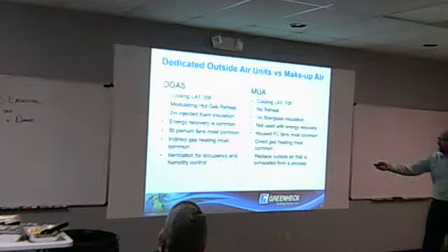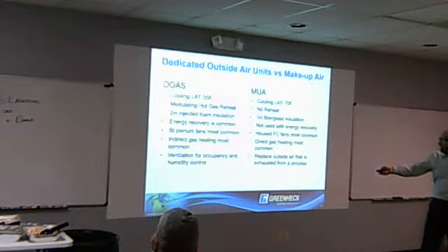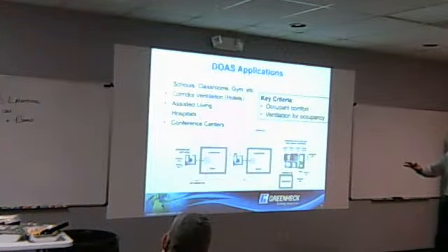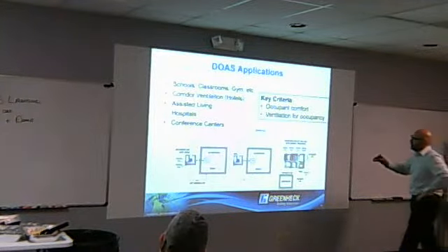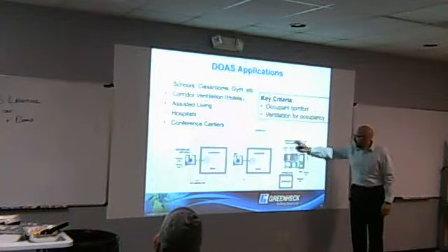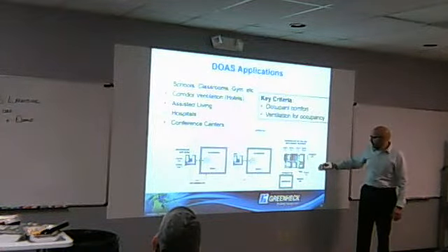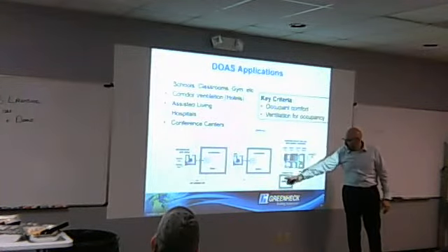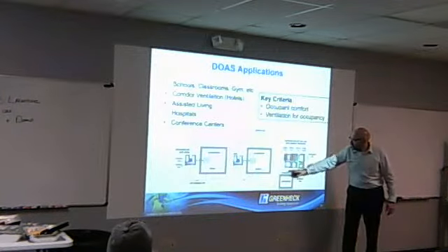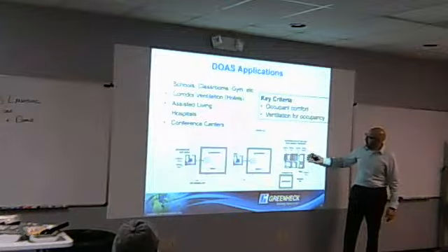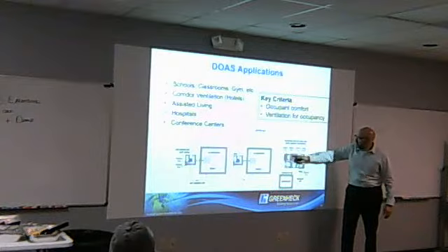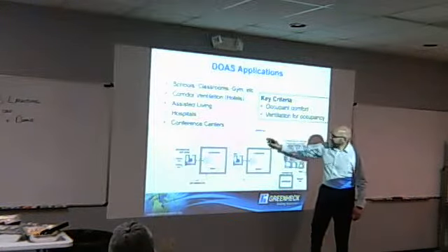Okay, occupancy ventilation, because of the occupancy and the humidity control versus replacing the exhaust process. We kind of touched on that. So this is how the system would look in terms of a configuration. We're focusing on dedicated outdoor air as occupant comfort and ventilation. So here's our dedicated outdoor air unit with energy recovery, bringing in our outside air. So maybe we're taking exhaust air from the restroom and the other exhaust air out of the classroom, bringing it through the energy recovery wheel, tempering that outside air so we don't have to heat and cool it quite as much. So this would be a cooling coil, heating coil, supply fan, and you're ducting that to the classrooms.